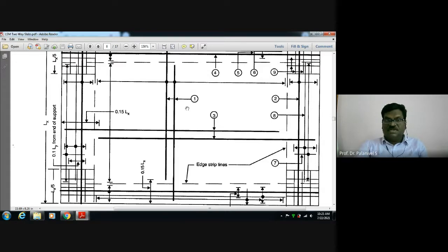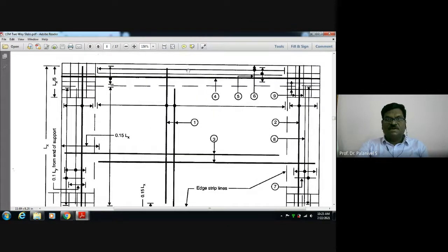Suppose you take it this way, the spacing is only 200 mm. We have seen just now the calculation. The spacing is 200 mm center to center. I have curtailed alternate bars. So the next bar introduced here will come up to this. Hope you will understand now. Now, what is the spacing between the bars? 200, another 200, 400 mm spacing. But in the calculation, 275 mm spacing is supposed to be. But it comes around 400 mm spacing.